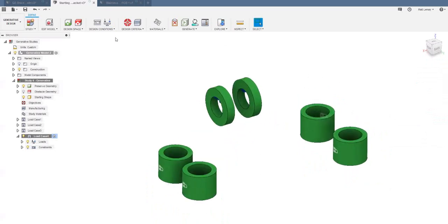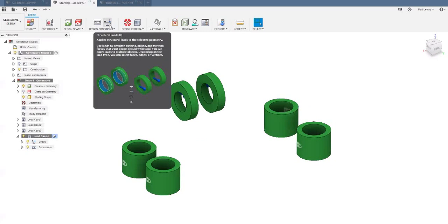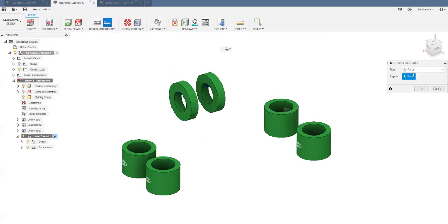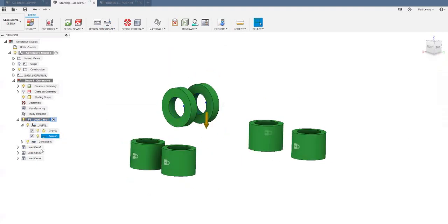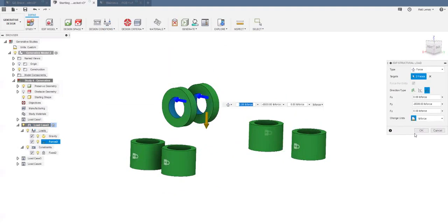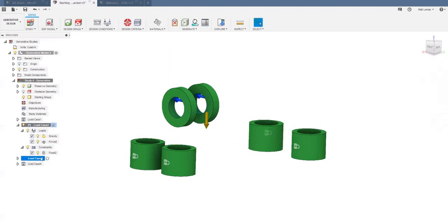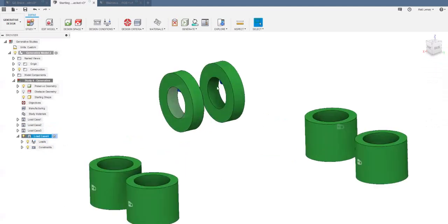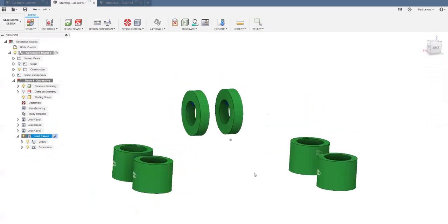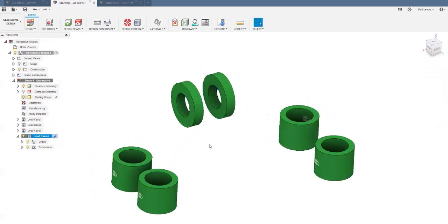Something we didn't cover here that I think is important are the other force types you can apply. So if you click on force again, you can see that we can apply forces like we've shown, or you can apply pressure as moments here as well. So very quickly to run through those loading conditions, we applied a vertical force, we applied horizontal force, we applied the force at an angle, and we applied that coupling moment where one force is applied to one face in one orientation and then the opposite in the other. So that's all that we need for our loading conditions at this point.